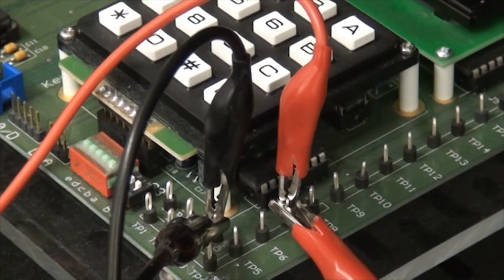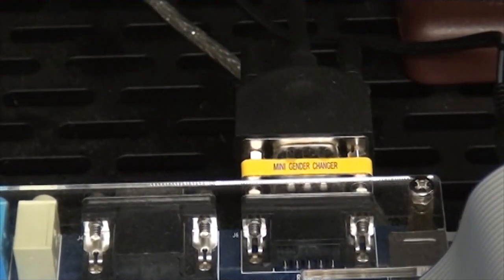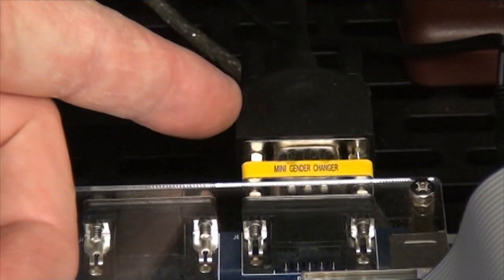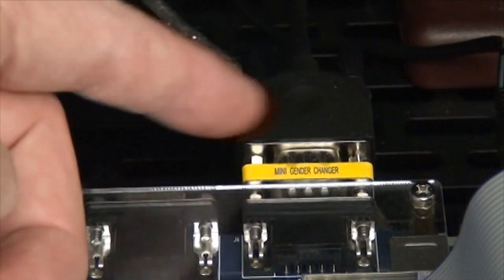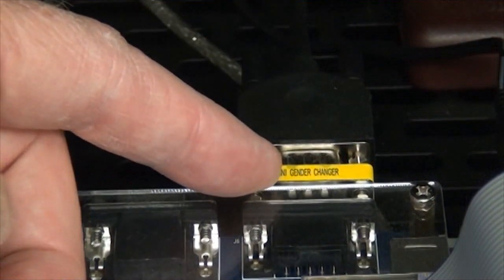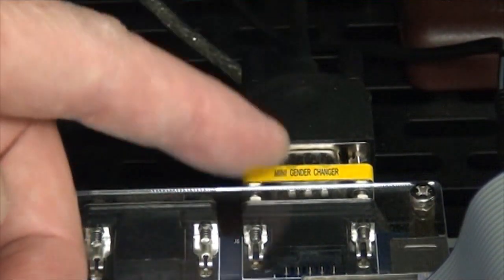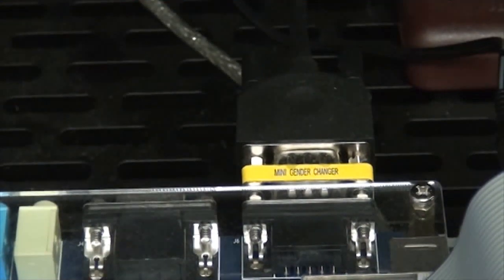As with the A to D and D to A lab, you'll find the connections will be to TP7 for the red connectors coming from the function generator, and also common grounds coming to the ground pin on the DE1 interface board. As far as other connections go, we're going to have to make sure that this RS-232 connector is connected to our DE1 board and also to your partner's board to make sure that the communication can happen between the two terminals.